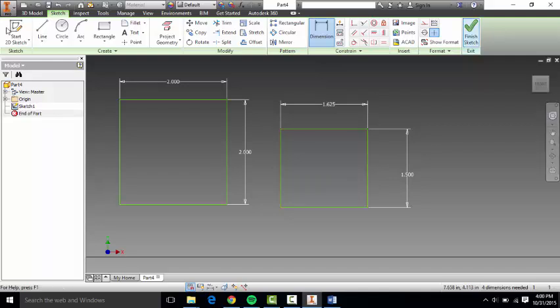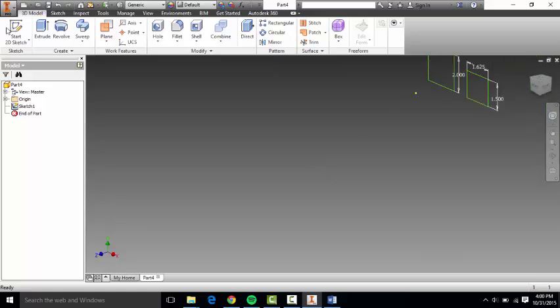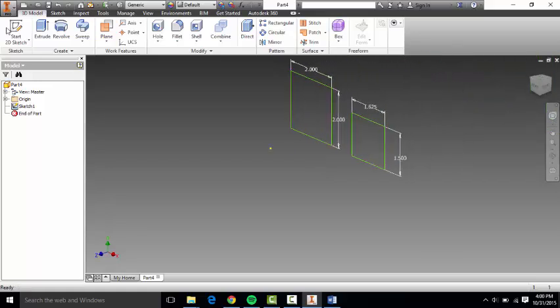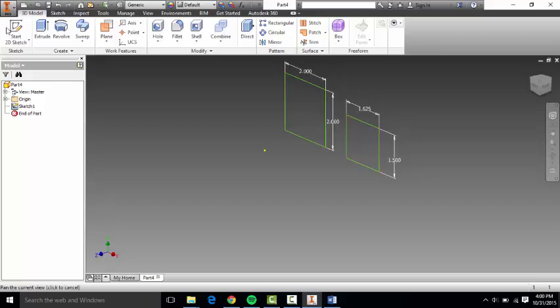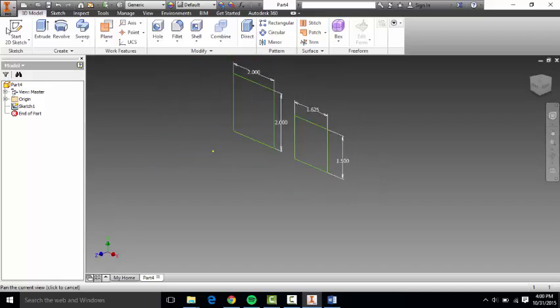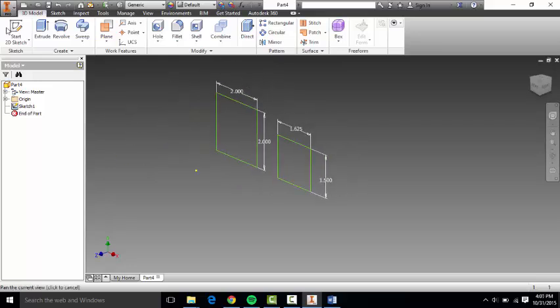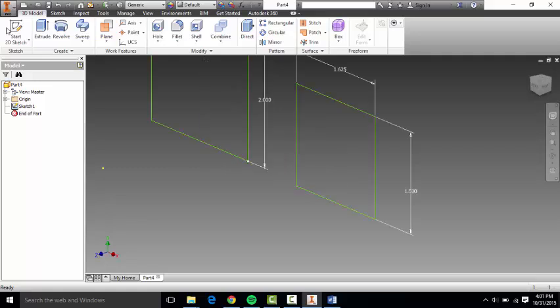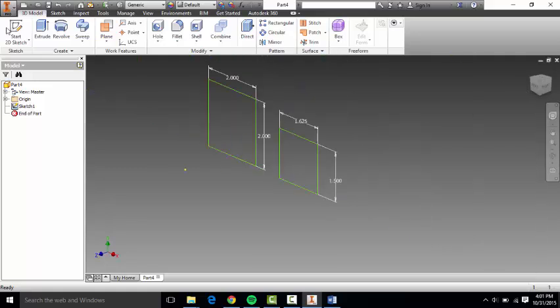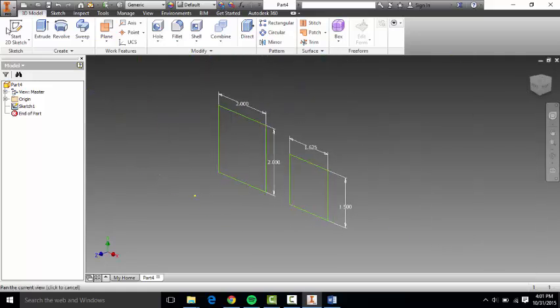All right, so let's finish that sketch. You just go up here to the top right corner, left click on Finish Sketch. It's done for you. You can zoom out with your scroll wheel, and you pan, which is what I'm doing now, by holding in the scroll wheel, pressing the button, and then moving your mouse. You zoom in by scrolling with the scroll wheel. Clicking and then dragging is panning.